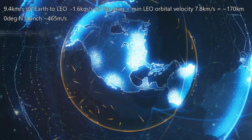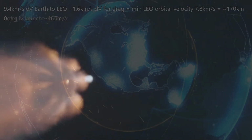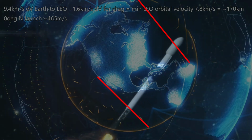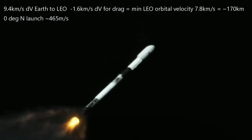The farther north or south from the equator you launch, the less effect the Earth's spin has on your velocity. If you need to get a large Earth observation satellite to a polar orbit, launching due south from Vandenberg Space Force Base, or perhaps due north from the European spaceport at Kourou, will both keep your rocket from flying over inhabited areas. But you won't get any boost from the Earth's spin, so we're back up to about 9.4 kilometers per second.